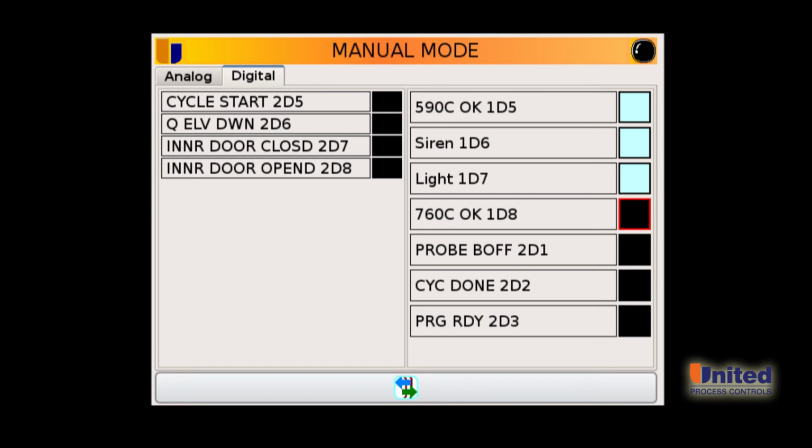If we have a digital output that's configured as a safety, those are still going to function as safeties, because right now I'm in a fault mode for my temperature interlocks, and it's going to maintain that as long as that condition exists.